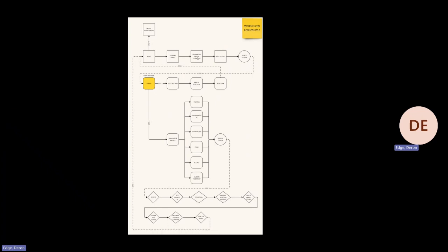Inside Revit, there's a generative design command where, instead of running one script at a time like in the original workflow, this will run that singular script or a multitude of scripts multiple times, kicking back a variety of results. It'll develop a report or feedback that lets us know, based off the matrix or the parameters you're interested in, which are the most efficient designs. At that point, we can go back out to Revit, select the design we're going to go with, and then go back into Forma.